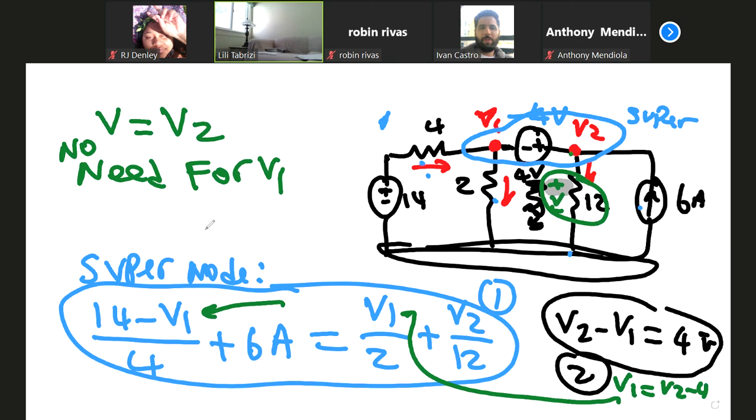Notice that if I have any voltage source, let's say plus or minus, if I assign a current, the current and voltage are not related because there is no resistance here. So the current always remains unknown, adding to the unknowns. I don't want to do that. So the voltage source connecting across is causing a problem in my nodal process.